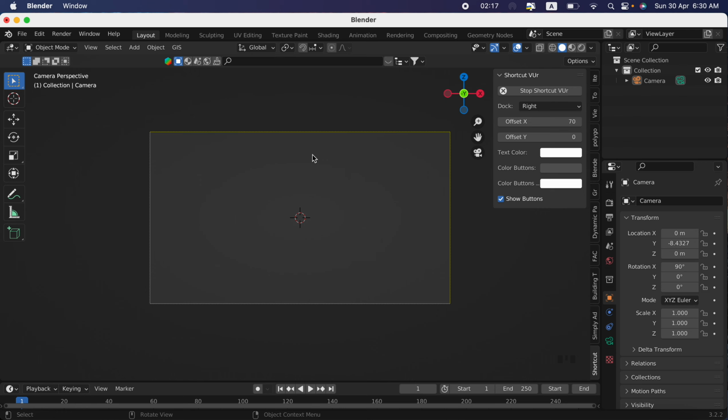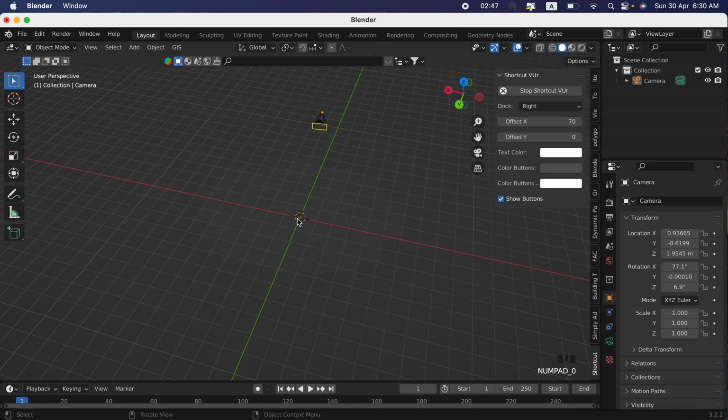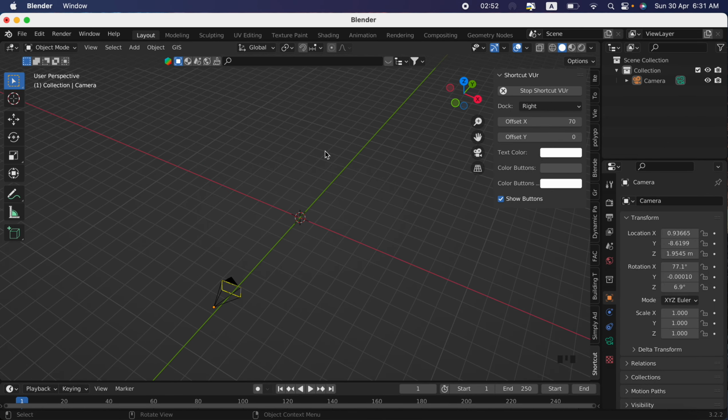And if I press Shift tilde, now press W A D S, what it is doing is moving in different directions. W to move forward, S to move backward, A to the left, D to the right. Shift tilde again. Now I can hover. Press the 0 button again and now I'm outside the camera view. Press it somewhere else and your camera is free now.